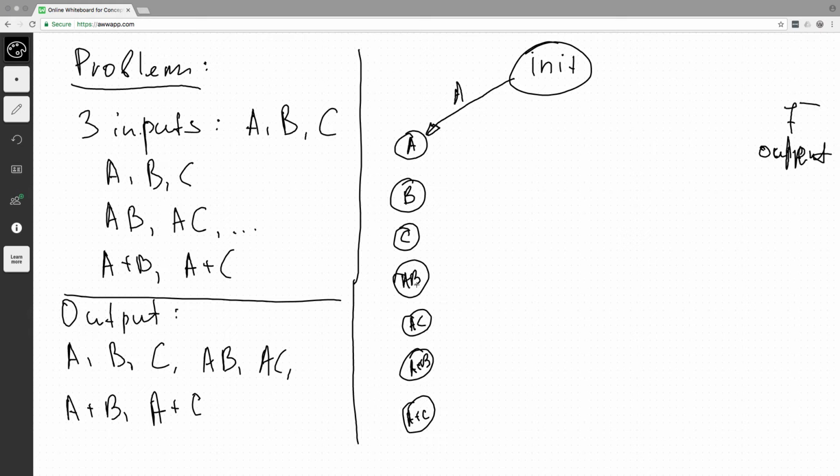So let me just illustrate this concept. When from the initialization state we move on to state A by means of signal A. Now, if signal B is given, which means a single key with the label B has been pressed, we move on not to a single state B, but we move on to the state A followed by B, the sequence AB, because we know that just before arriving here, we have been in state A, and this is the guarantee that input A was followed by input B. So from A, we move on to B.